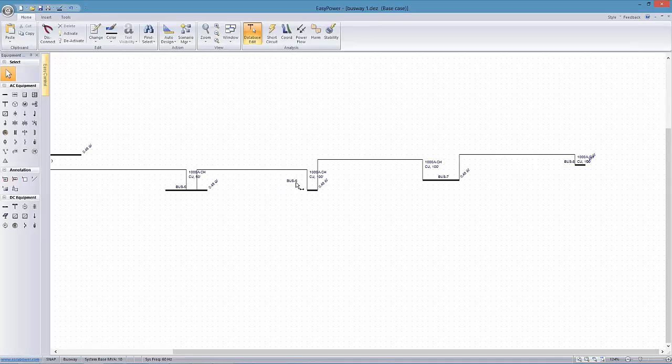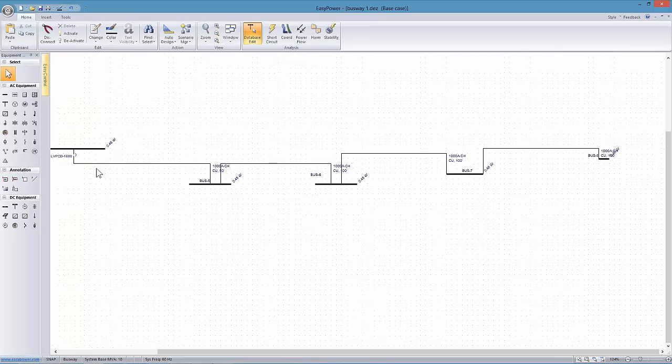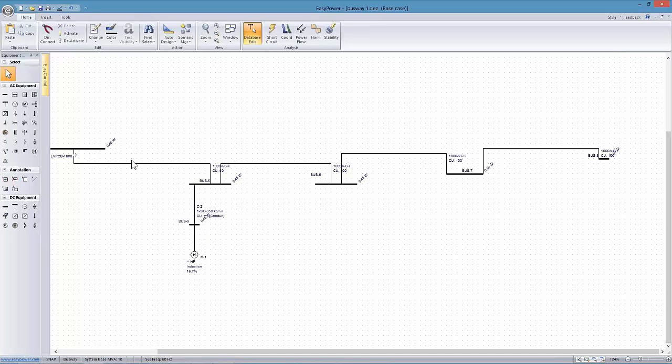All right, so now in terms of setting up the equipment that's coming off of the drops, I can either lump these or detail them as much as I want, but let's say within this first 50-foot run, I have a 25 horsepower motor that comes down off of a 10-foot cable from the drop. Now the physical drop may actually be out here at 25 feet somewhere, but since I'm averaging it, I'm using the actual 15-foot cable that's going to come down from the drop at the 25-foot point. And let's say each of these has a fuse.